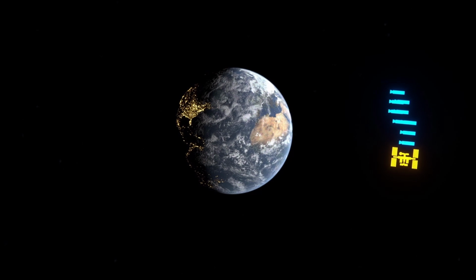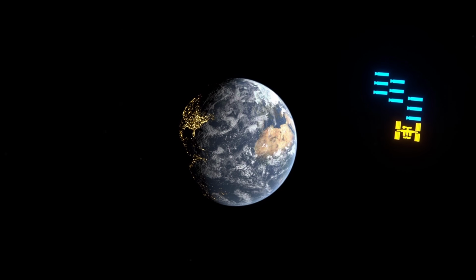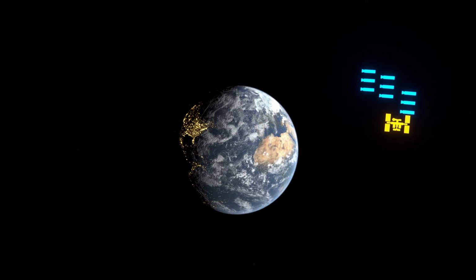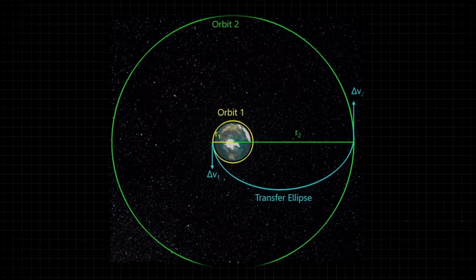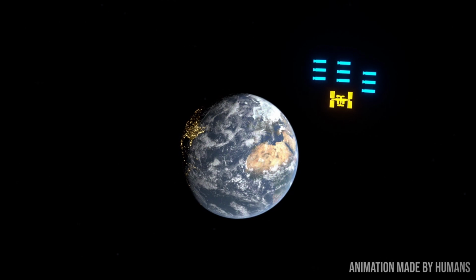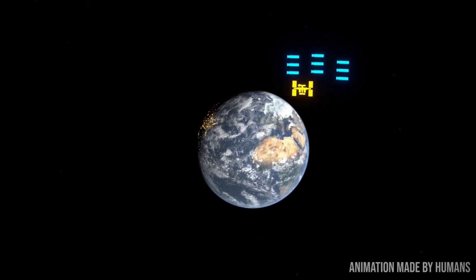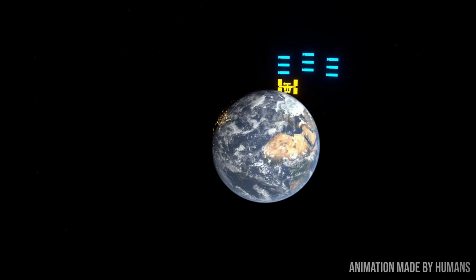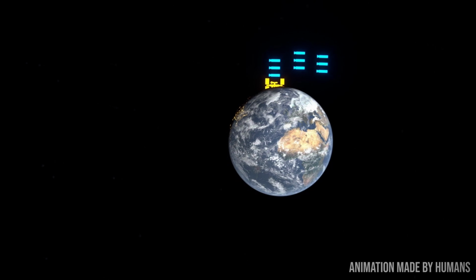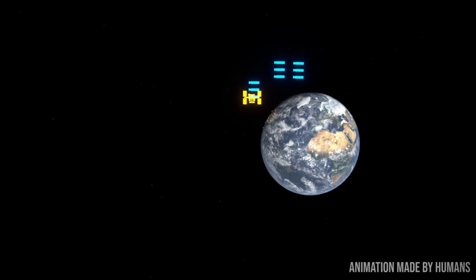After much deliberation, we figured the simplest approach was just to have the rocket pods assume a parking orbit just above the orbit of the receiving station, where the rocket pods will simply wait for the correct orbital period alignment, allowing for a gentle Hohmann transfer and rendezvous. Basically, they just kind of fly above, wait for their time, and then dip down and rendezvous with the station. And if you think about it, this parked orbit, this queuing, essentially acts itself as a laydown yard. So the receiving station itself can devote less resources to storing these actual rocket pods.